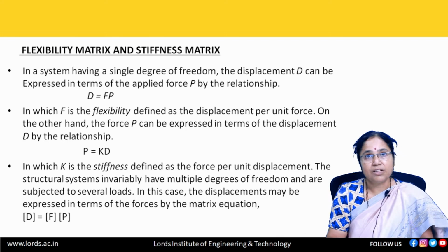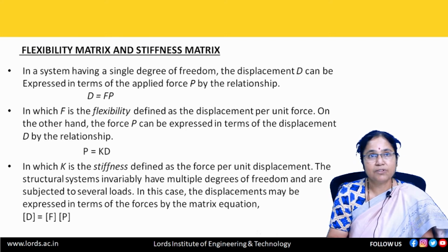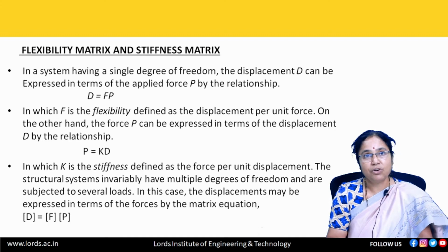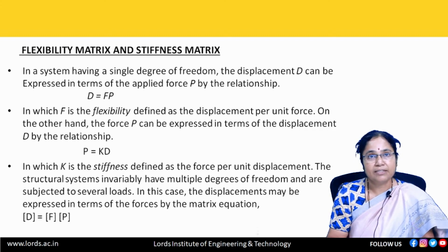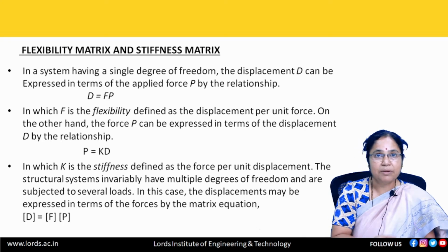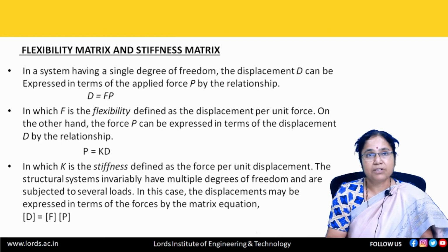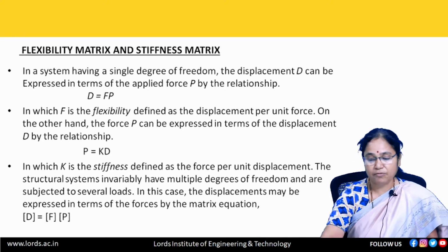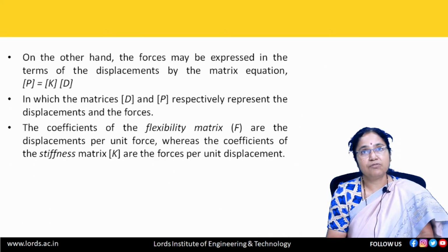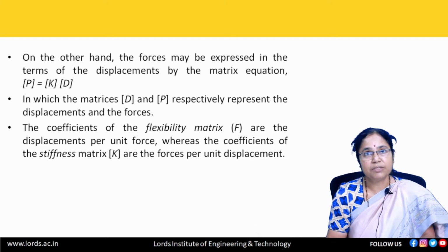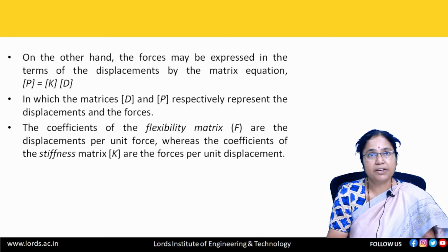On the other hand, the force P can be expressed in terms of the displacement d by the relation P equal to K d, in which K is the stiffness defined as the force per unit displacement. The structural systems invariably have multiple degrees of freedom and are subjected to several loads. In this case, the displacements may be expressed in terms of the forces by the matrix equation D equal to F into P. On the other hand, the forces may be expressed in terms of displacements by the matrix equation P equal to K into D, in which the matrices D and P respectively represent the displacements and the forces.